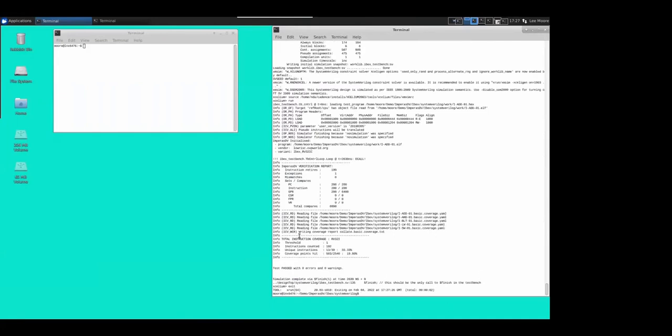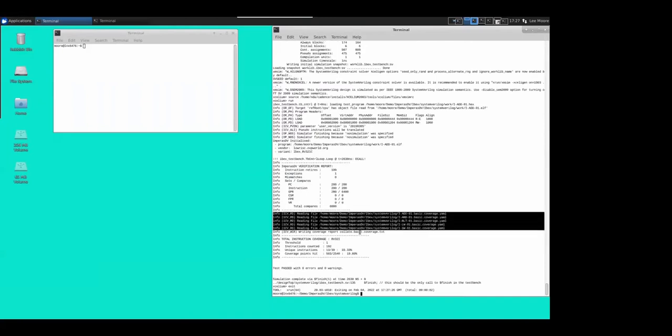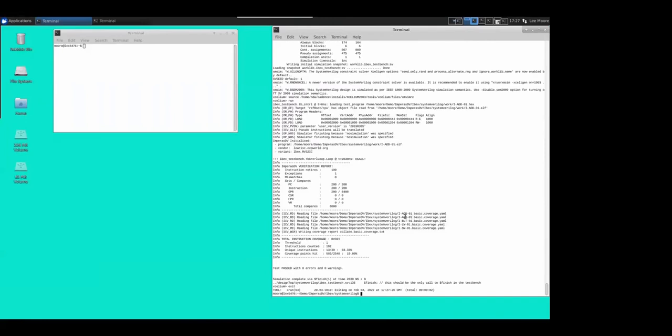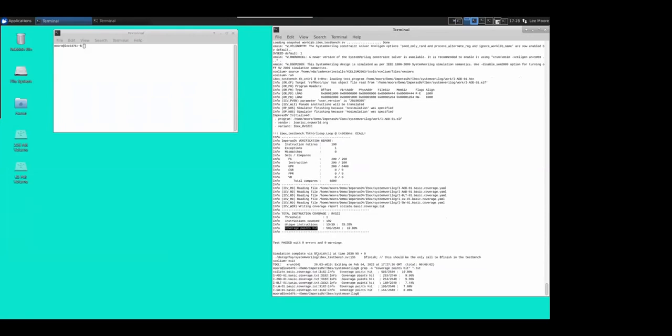So we see here for this last test that ran, which I'm not sure which one it was actually, but importantly here we see the 5 tests that we've aggregated. And this is the add, the and, branch if less than, load word, store word. And you can see here we've hit this many coverage points, so 503 out of 2,540 coverage points. In fact, let's do this, if I grep for this description here in all of the coverage files, excellent. That's what I would hope to see.